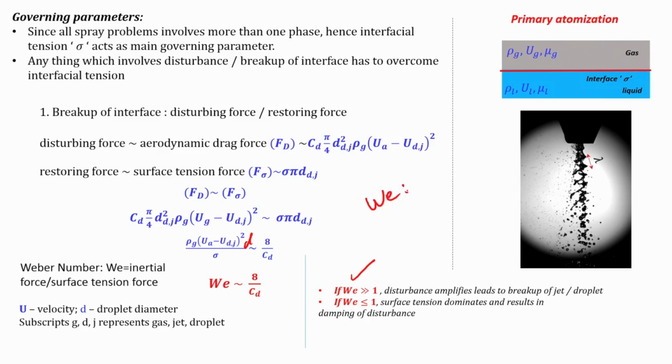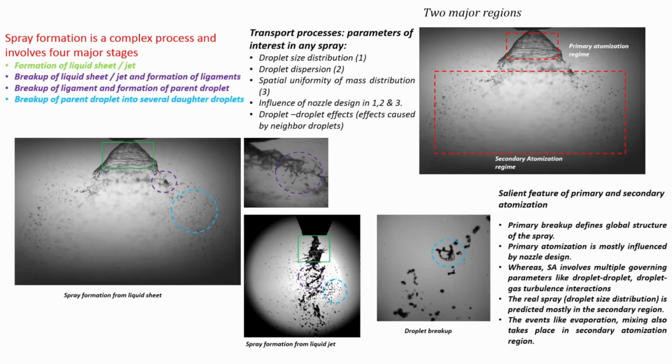It is the most important parameter in whatever you do. The Ohnesorge number takes into account the Weber number, the viscosity and the surface tension, all of these combined. Most of the maps will be done by Weber number.